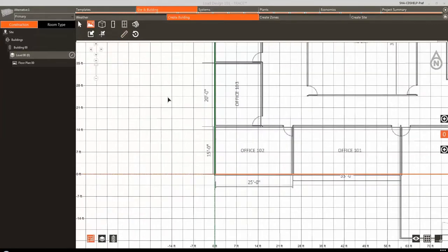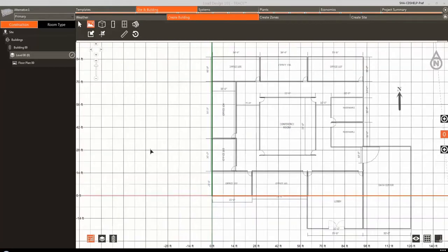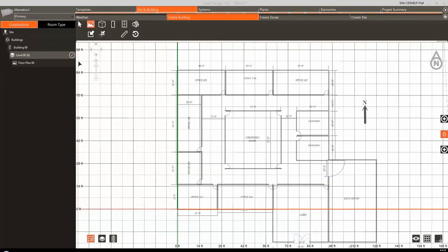It is very important that the floor plan is scaled properly. Otherwise, the rooms will not have the correct dimensions when they are drawn. We recommend using one of the largest dimensions to scale images. In other words, use one of the building's sides, not a doorway or a small wall. If the image needs to be rotated, this can be done using the Rotate tool. Now that the image is scaled, we can start tracing over it.